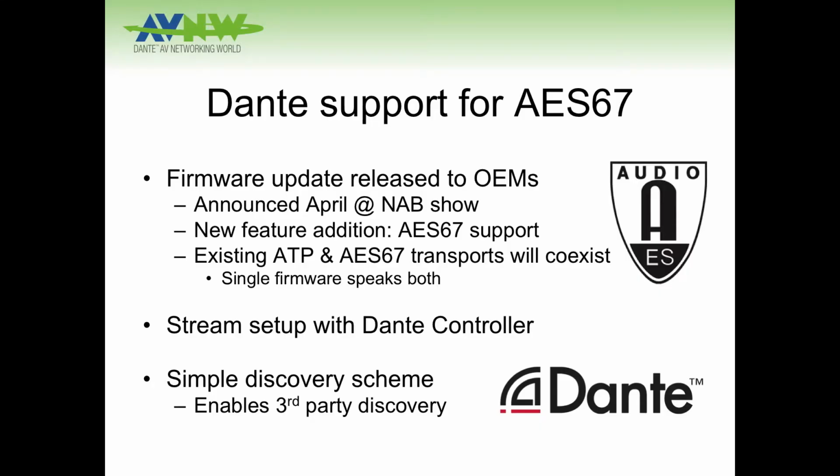Stream setup for AES67 will be inside Dante Controller, and we're also using one of the simple discovery schemes specified in the AES67 specification. So that means that third-party devices will be able to use a standards-based discovery protocol in order to discover Dante AES67 streams that are available on the network. So that's all I wanted to say about standards.